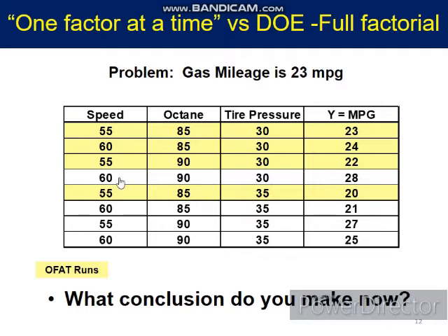When you set up your experimentations, depending on the number of factors and levels, when you use certain software, either Design Expert, Minitab, so on and so forth, it will tell you the number of runs, the number of experimentations that you need to run. So if you turn this particular case study into a full factorial design experiment, the number of runs would be 8 runs. You have to run 8 experimental runs. Compared to one factor at a time just now, we have to add another 4 runs, as shown here in white.